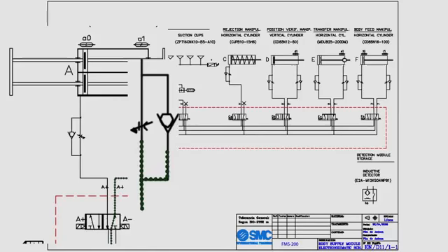This is a flow control that allows us to meter the amount of air in or out. So we have a restricted orifice right here, and the next one we have a ball and seat. The air is typically going to want to blow the ball off of the orifice because it would require much more energy to go through the restricted orifice. So it takes the path of least resistance. So we blow the ball off of there.